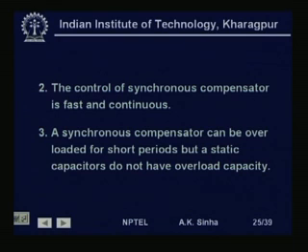The advantage of synchronous compensator is that we can very smoothly vary the reactive power absorption or generation by this machine. Another advantage of the synchronous compensator is that it can be overloaded for short periods, whereas this is not possible with static capacitors, because if you try to overload them, they will normally puncture, whereas these synchronous machines have some amount of overload capacity for short periods.